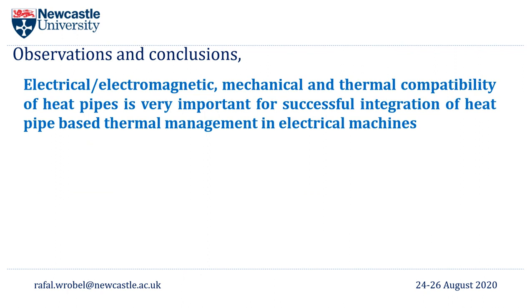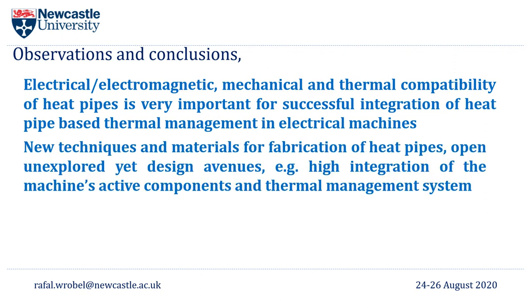When it comes to future work, we will need to focus on various compatibility issues: electromagnetic, electric, mechanical, thermal, etc. And that is necessary to provide successful integration between the heat pipes and the electrical machine. Also, new materials and new fabrication techniques open new avenues for integration as discrete components, but also for creating new active components that already have the heat pipes integrated, for example, when using additive manufacturing.